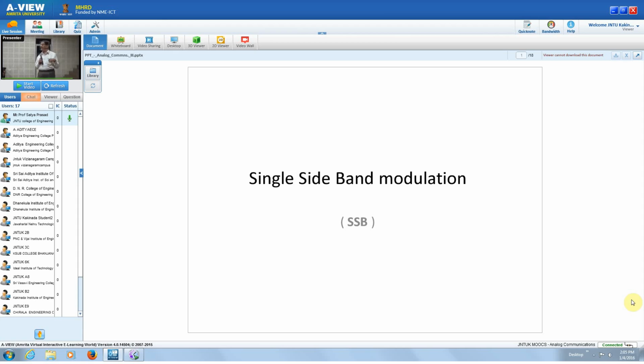So, to avoid that, we are generating the carrier from the received signal itself, by going for a squarer, a divider, and a filter. First you square this input signal, then you pass it through a filter and then divide it to give you the required carrier frequency in coherence with the received signal, so that we can use that in the coherent detection and get back the original transmitted baseband signal.